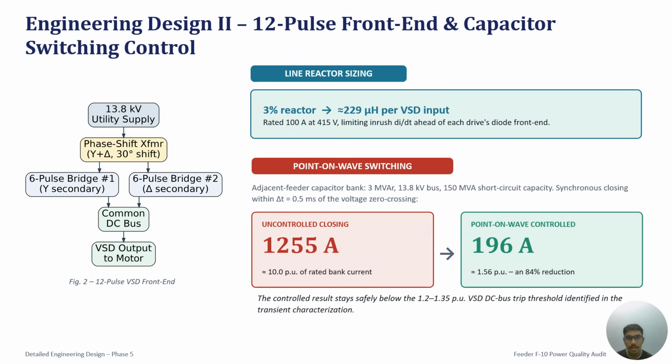For the capacitor bank, a megavar bank on the 13.8 kV bus with 550 MVA short circuit capacity. We specify point-on-wave switching with synchronous closing within half a millisecond of the voltage zero crossing.